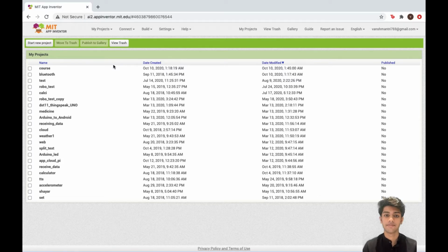The way we are going to achieve this is that, let's say every time on is pressed, a particular character, let's say A, gets sent to the HC05 module. Now this module serially communicates this to the Arduino Uno. So at the end of the day, whenever we press the on button, the character A gets received by the Arduino Uno, and we can program that, okay, if A has been received, we want to turn on our onboard LED. And similarly, every time we press the off button, we are sending the character B to the Arduino Uno, and once received, we can program it to turn off the onboard LED every time it receives B.